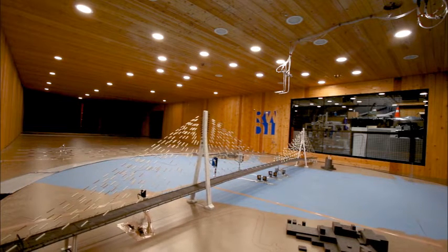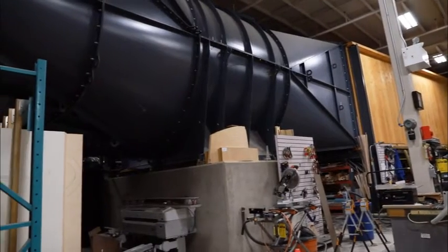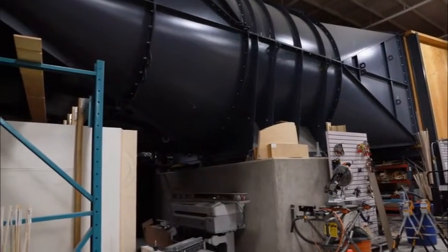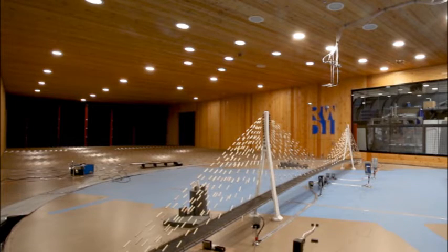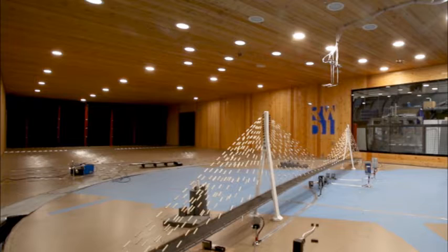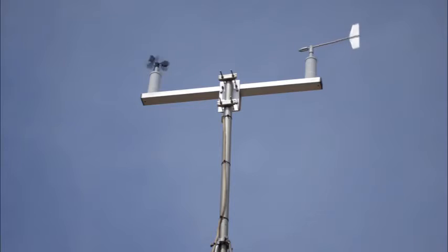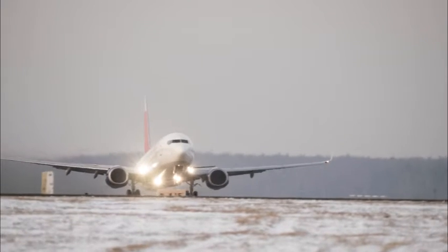In the wind tunnel, we have some large turbines that spin at high rates of speed to force air through an enclosed chamber. And we can manipulate the wind that these turbines are producing to match the local wind data for wherever we're testing a project. We take the information from the local wind collection sites, such as, in this case, the Detroit airport, and we scale that and factor it to match in our wind tunnel.